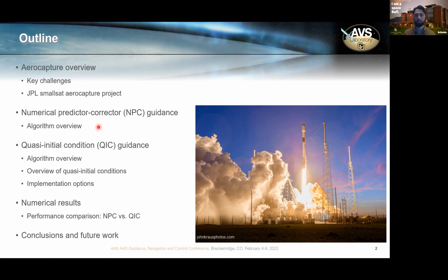features as compared to NPC is that it involves a significant pre-compute step. So this green shaded portion is performed only once and done sometime before atmospheric entry. We've been doing it at 10 minutes prior to entry because that is the time of the final navigation update to the spacecraft in this reference mission. And it also includes this purple shaded region that's performed every guidance call.